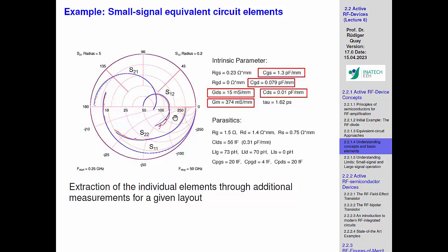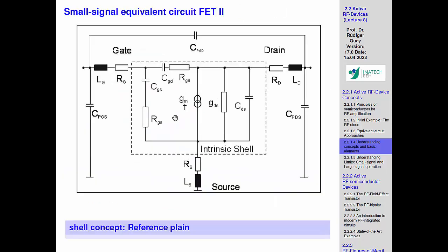Yeah? So in this case, we are not really measuring currents. The only thing we are doing, we are extracting, based on these high frequency parameters which we have here, the representation of these FETs. Yeah? And you see here, there's suddenly a lot of additional elements appearing, which we need to consider. So for example, we already talked about the GM and the GDS.